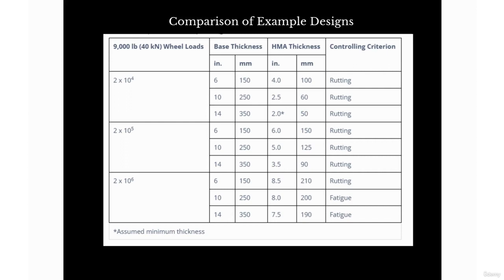So this then comes to that cost benefit analysis. Also, where you are on site, is the aggregate available? Can you have enough aggregate to have that 350 base? If you can, which means you won't need an HMA thickness of 190, it's better to have this thick 350 base and maybe an HMA of 50, because that will save you money. Hot mix asphalt is more expensive to procure, and more expensive to place on the road than finding aggregate.